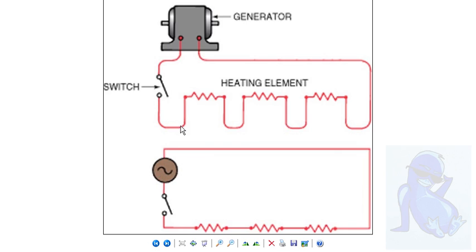This little symbol here represents the power source, and that's essentially a sine wave. And that's your power source, and this is your switch. And going this way, this little squiggly line represents resistance or a load. Where you find resistance, you find the work being done. And they're all strung together in a row, which means they are a series circuit.